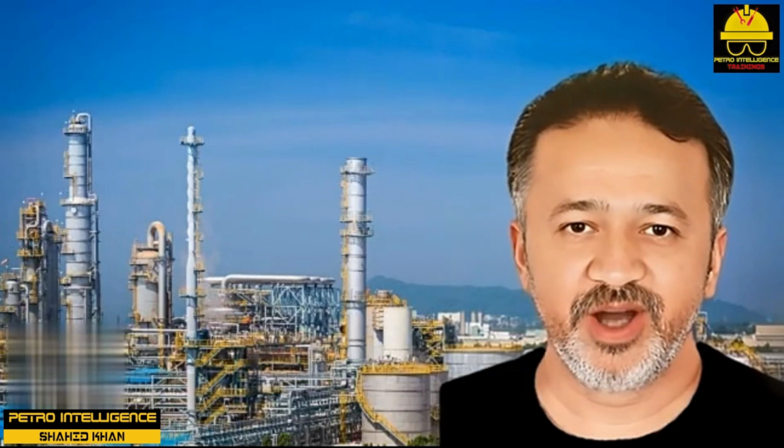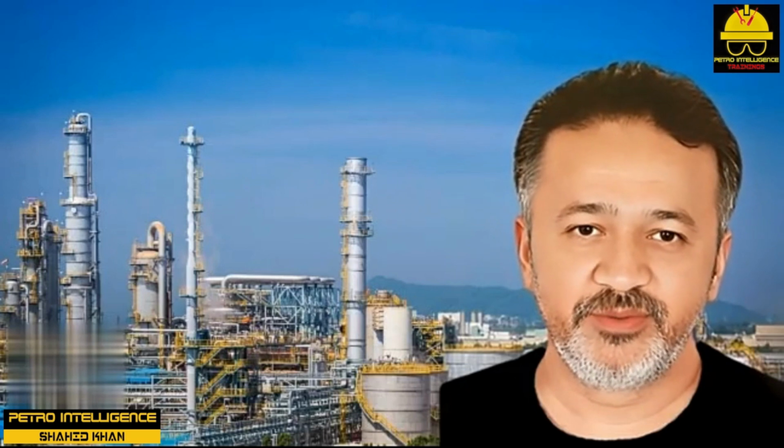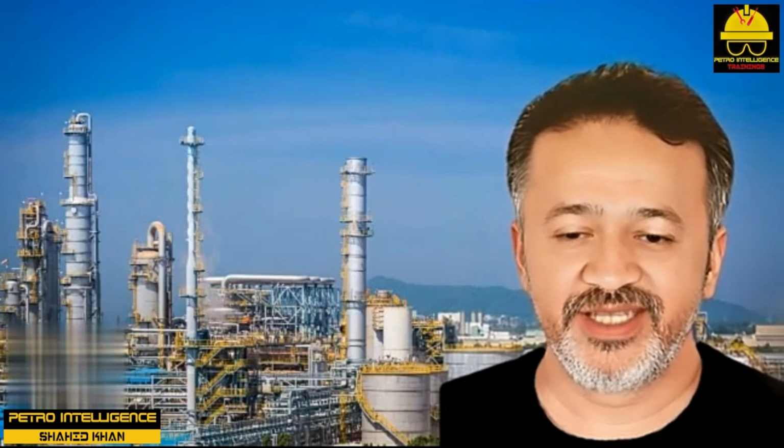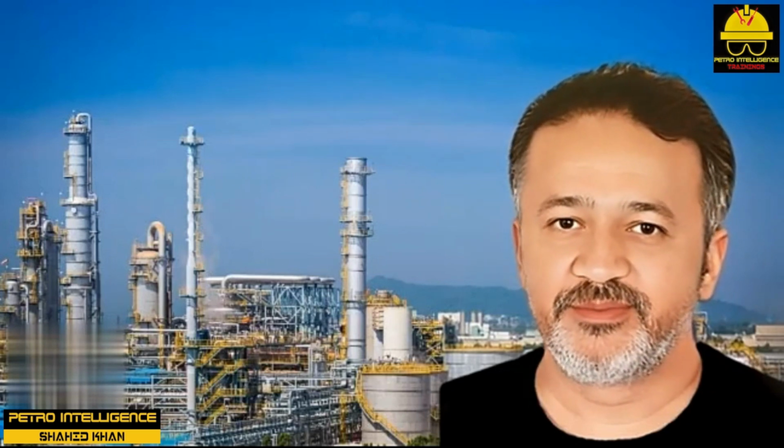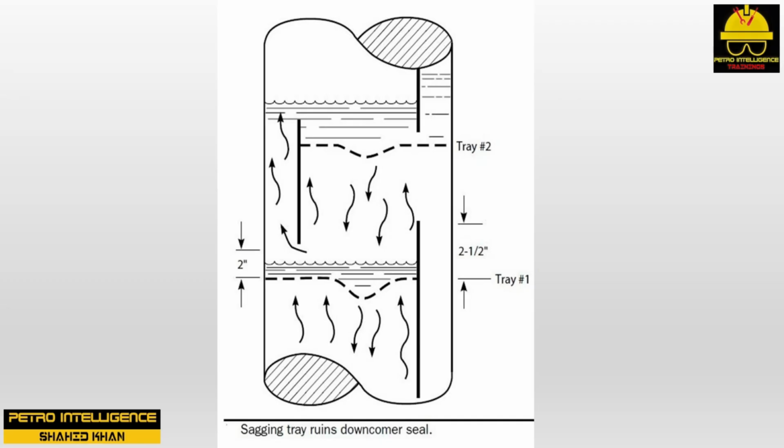Loss of downcomer seal. I told you in a previous video that the top edge of the outlet weir is maintained about 0.5 inch above the bottom edge of the inlet downcomer to prevent vapor from flowing up the downcomer. This is called a 0.5 inch positive downcomer seal. But for this seal to be effective, the liquid must overflow the weir. If all the liquid is weeping through the tray deck, there will be no flow over the weir, and the height of the weir will become irrelevant.